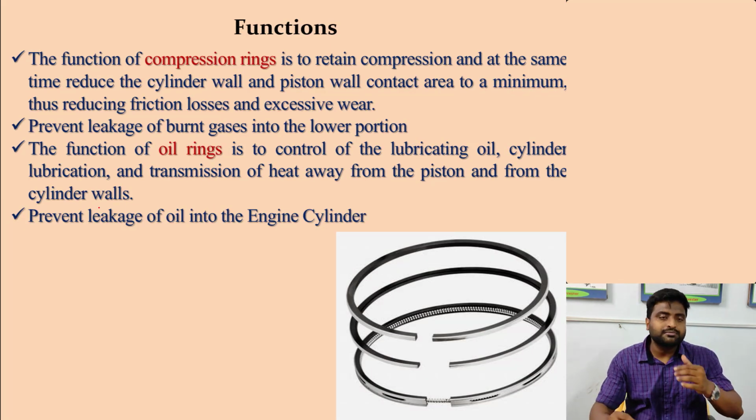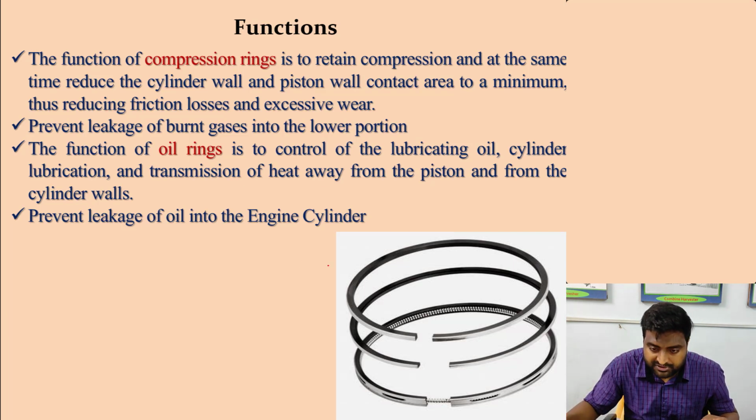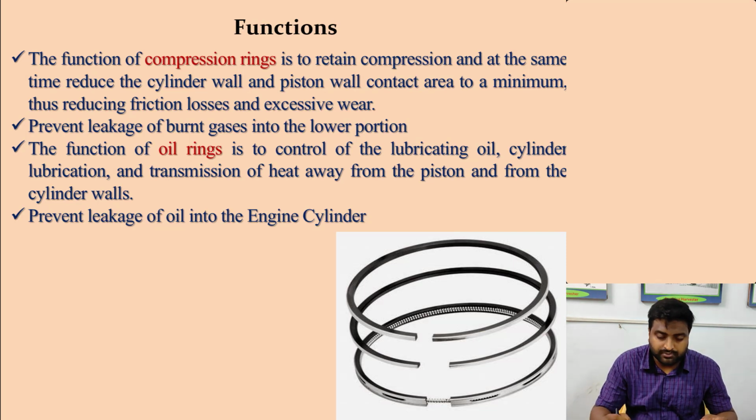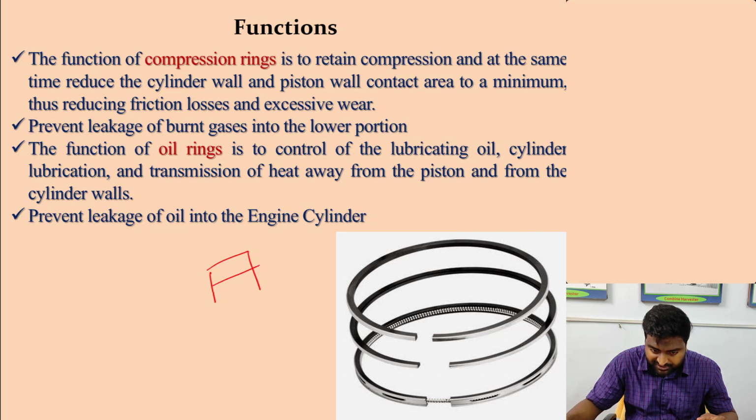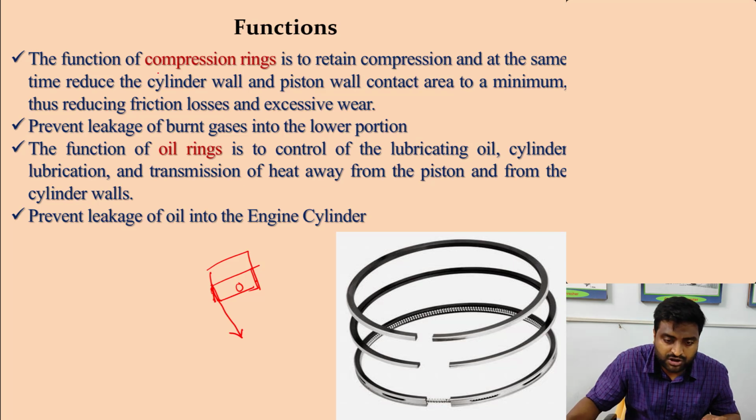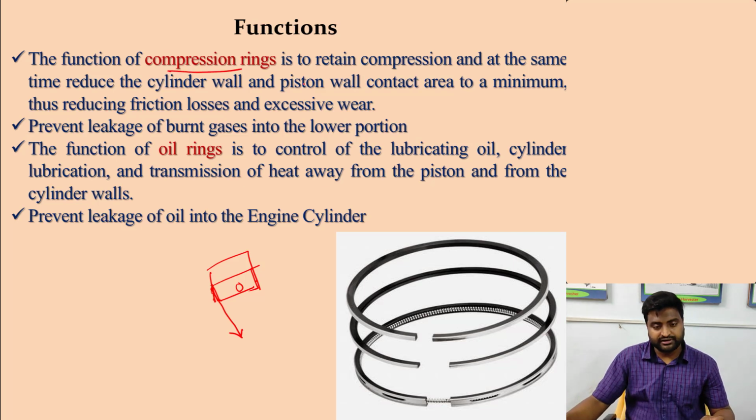What is the function of the compression ring? As the name suggests, it will never allow the gases generated to pass through. Sometimes, if the piston and cylinder are not leak proof, the combustion gases may go to the crankcase and create a problem. So to make the contact area between the cylinder and the piston leak proof, the compression rings were given.